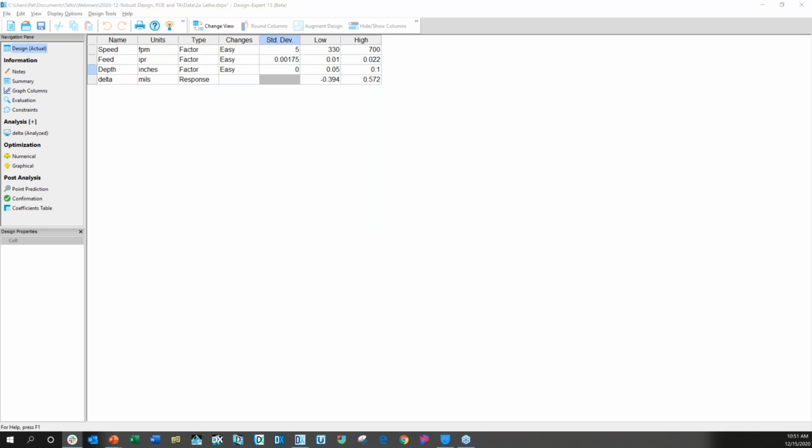Now, we did that so we could fit that into a model, and then we could do the propagated error for that. Now, what's different is when you go to do the optimization, now you've got a model that's got control factors, which in real life you're going to control, and you've got this factor ambient temperature, which you control during your experiment, but you're not going to be able to control in the real world, but it's in your model. So you put that in, and you put in what its variation around its nominal value is.